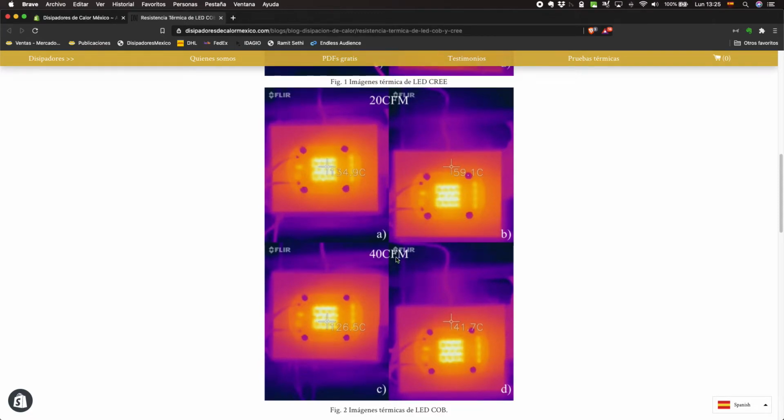And in this case, what is important is that I used this temperature here, obtained by the thermal camera, and I compared it to the temperature obtained by the thermocouple. This way, I am normalizing this temperature with respect to the temperature obtained by the thermocouple, and I would get a better approximation of the real temperature, because this value is normally not very precise. It gives a good idea, but it's not very precise.